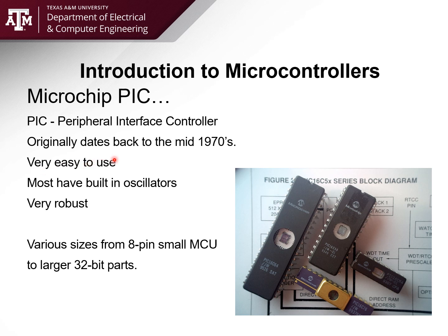I've actually taught embedded systems in an afternoon for a lot of students and other engineers because effectively, if you can download the tools, I can pretty much get you up and running with a PIC in probably 30 minutes. Essentially, apply power, hook up the programming pod to it, write a simple program, and you could be blinking an LED literally within minutes with a PIC. They are very easy to use.